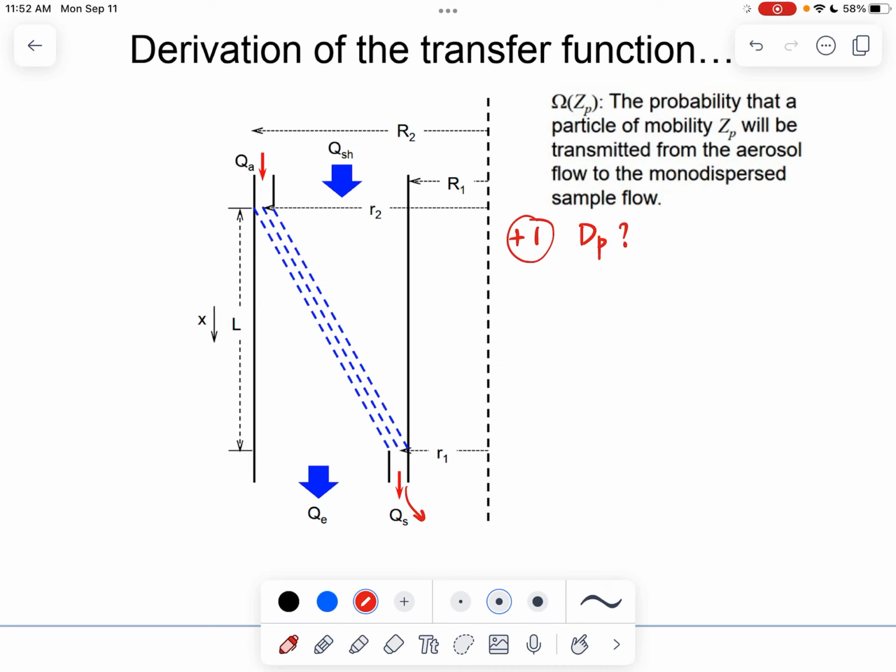If they carry one charge only, then does it mean that the aerosols we collect from the downstream are all of the same size? Right, so we mentioned that the ideal situation is that particles carry the perfect size such that they enter from the center of the aerosol inlet and exit from the middle of the aerosol outlet, right? But are there other sized particles getting selected? There will be, right? So let's assume, for example, if we're still talking about this perfect size, then if we move around this inlet, because the aerosols are not only being introduced from the center,